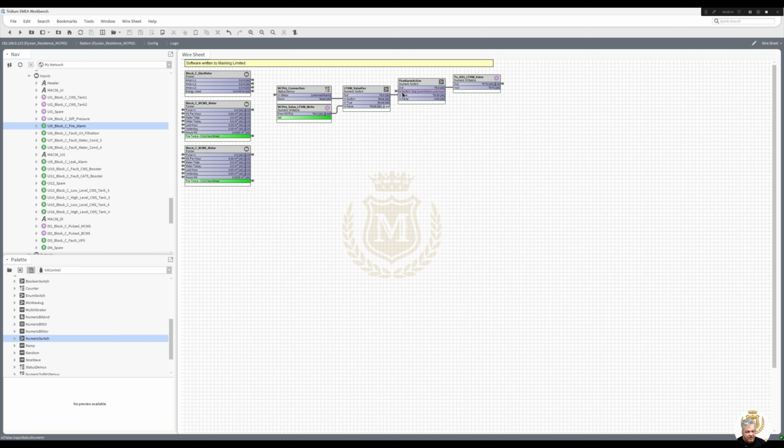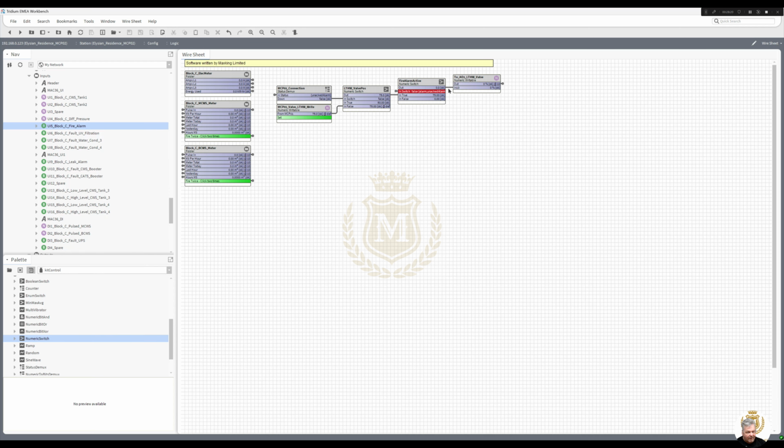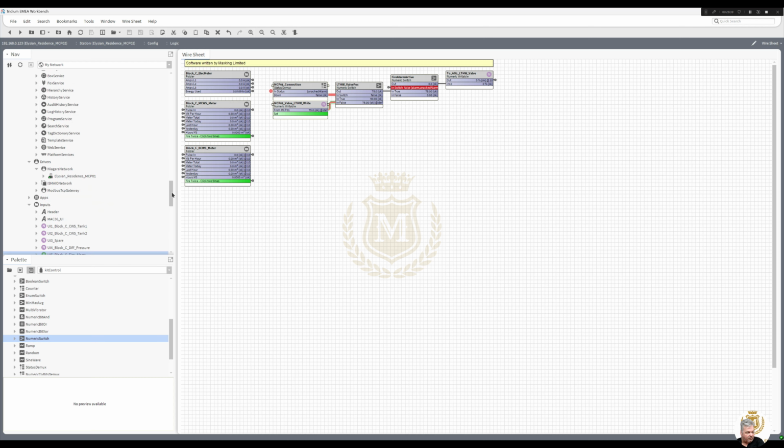So now I'm bringing the 75 across and then put it into fire, emergency auto. We're now in fire, we're closing the valve to 0. So we've linked the fire alarm into that as well as the network. I can keep that like that. And that's the only little bit of logic we are doing on there. So that's that finished with.